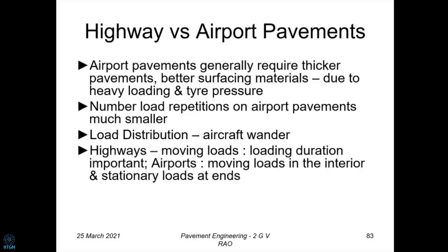When you have a runway, its characteristics are not going to be the same from this end to that end. The ends are different and the center is different. And in some cases, the center portion of that runway is going to have much more thickness, that means cross-section wise, and the edges may have different kinds of thicknesses also. Please see that. That means the ends of the runway, say 10% at the ends, if you consider, let's say 1 kilometer, so 10% of that, 100 meters on either side, is going to be of a different kind. Sometimes it could be 500 meters also.